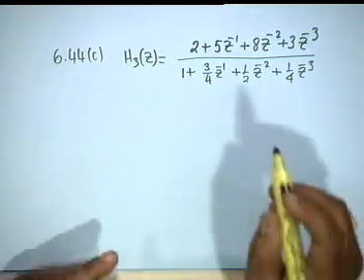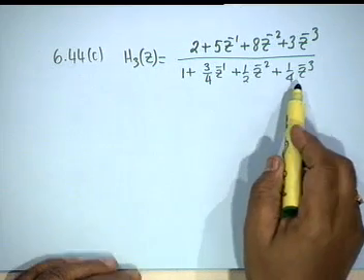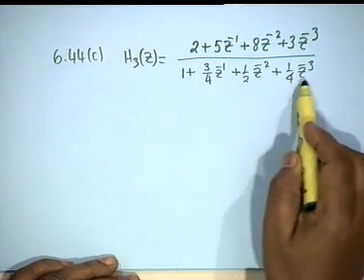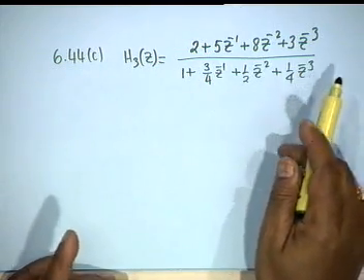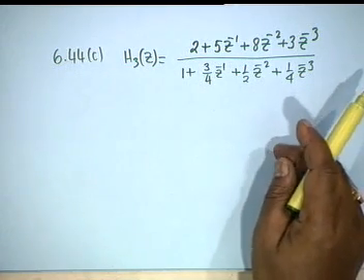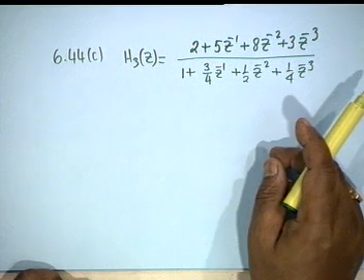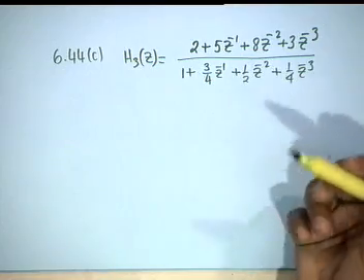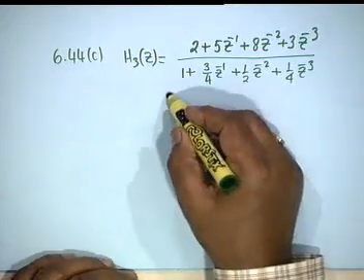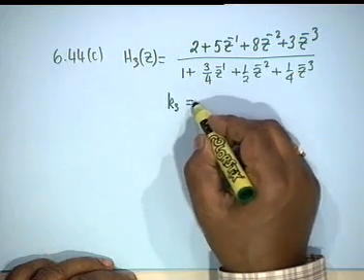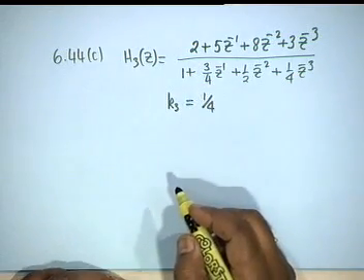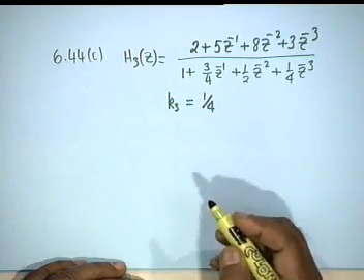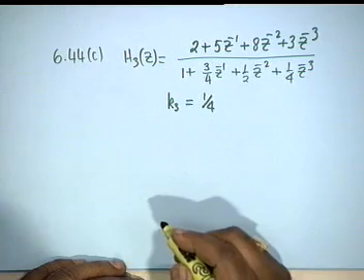The first thing to do is to realize an all pass filter with this denominator and the numerator Z to the minus 3 D3 of Z inverse, okay, all pass filter. Now, you do not have to write all this, because you can see that for the all pass K3 is 1/4, okay. Then you have to find D2Z.